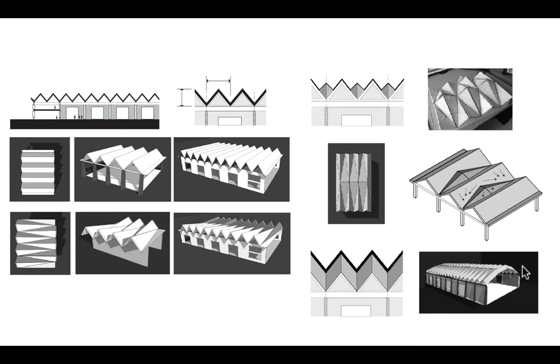So here we're hacking together a couple of different ideas, right? It's kind of a beam arch, very, very shallow arch, so it'll still take some bending, but we're basically making that folded plate now kind of shaped so that it gets out of the way of the tensile region on the bottom of the beam, right? This is going to be more in compression than in tension. That's kind of one little hack that we've done. We've made the beam into a beam arch. And then the second hack is to make that beam not out of a solid, heavy material, but out of these thin, lighter weight folded plates, right, that take away most of the dead weight and allow it to span quite a bit further.